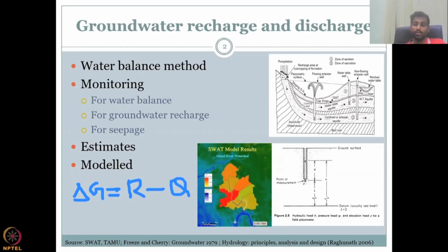As I said, the parameter variable differs. You can put rainfall as R or P, etc., but it's all the same. How you define it is very important. So in this equation, I'm defining it as del G, which is your difference in groundwater level, which is the fluctuation, and is nothing but your rainfall, the water coming onto my land, minus the runoff. So if I subtract the runoff volume, whatever volume remains is going into the ground. Remember, there's no ET, no evapotranspiration, no other losses, because I'm taking a very specific case study where I don't have all these.